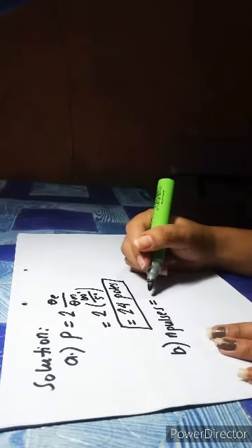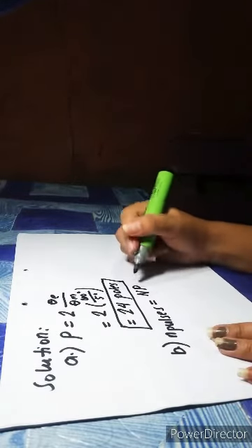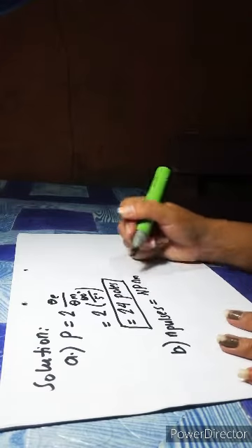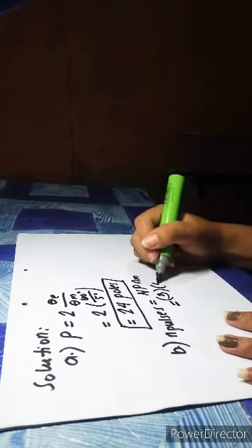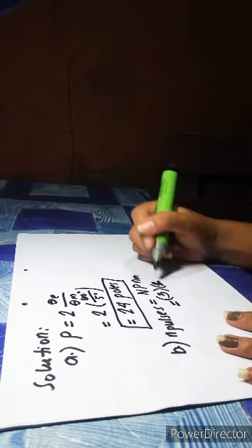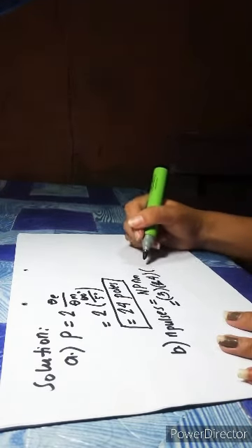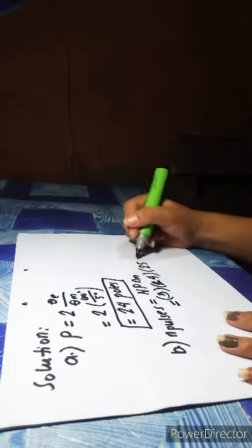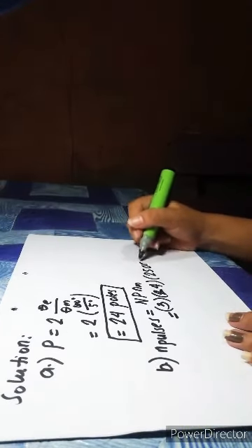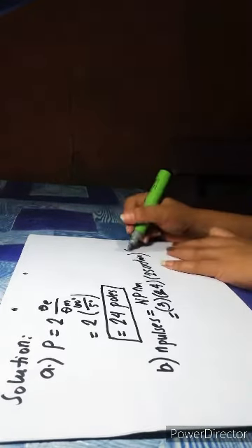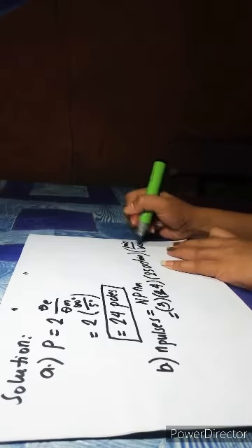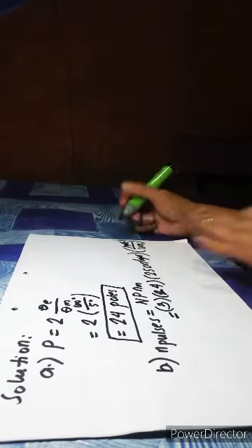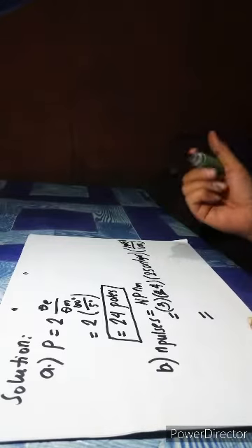So the pulse rate is equal to the number of phases times the number of poles times the speed, or 3 phases times 24 poles times 250 revolutions per minute, where 250 revolutions per minute is converted to revolutions per second: 250 revolutions per minute times 1 minute over 60 seconds.